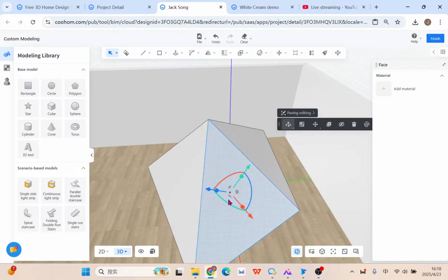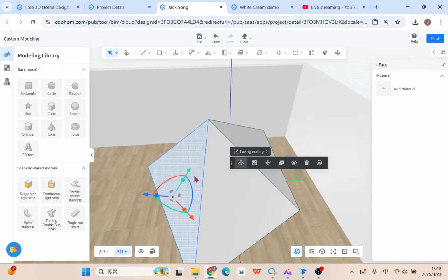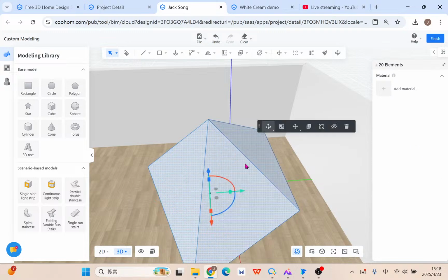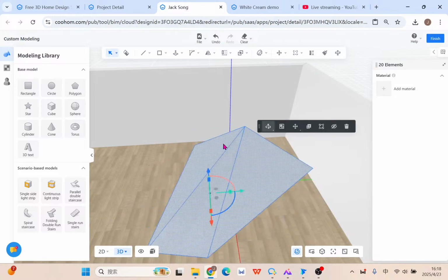You see here the changing. If you want to delete that, holding down the shift button, click randomly on one surface, holding down the shift button, double click. And now they're all selected. Once you select that, group them up, of course, and rotate as a whole unit, or you can just delete. And also if something is hiding away, you can just use hide or connect faces. Wow, that's really a useful function.